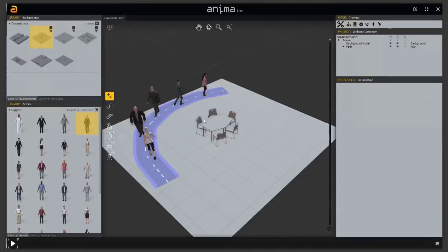Okay, Anima centers on top of the origin of the 3D scene in Anima, according to the geometry density of the models we are importing. Okay, so reduce details, export only those elements you want, and keep in mind this way Anima updates the background model. Okay, this is very, very important.